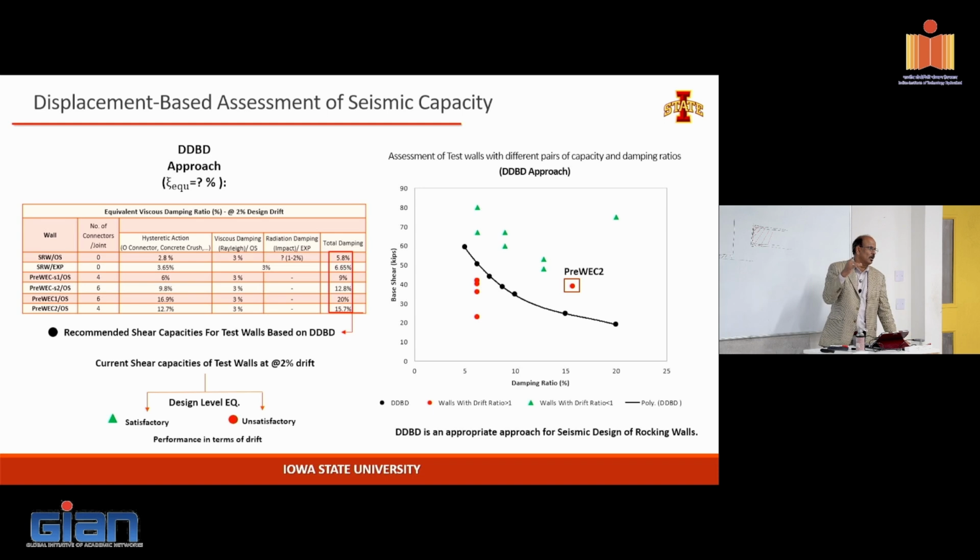The wall comes in, the floor comes in, you run the rebar into the floor, into the wall, and then the wall has to now take the floor with it. So I think I showed a slide earlier, and I'll show it again. When that happens, even the plastic action that takes place within the floor will restrain the wall from going. So it will not rock as much as you envision as an isolated wall.